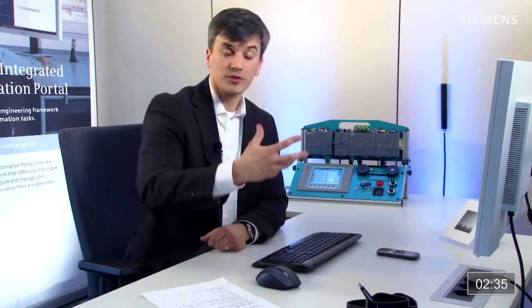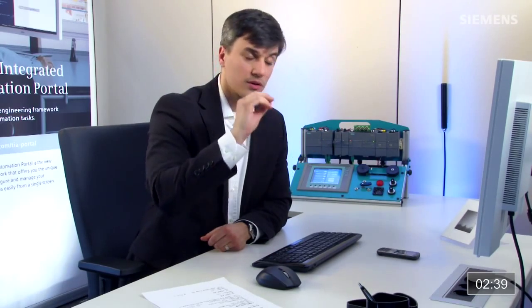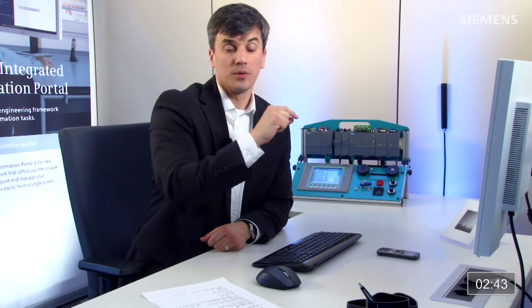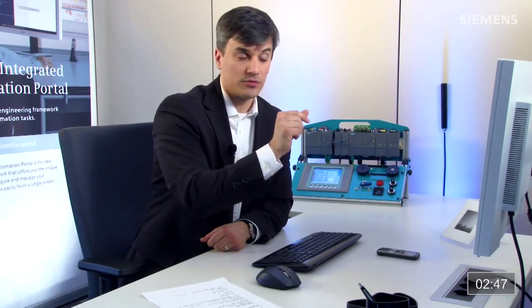So the next step is we want to give focus to the PLC and click the download button. Ultimately, if you think about what we've been able to do, we were able to scan the Profinet network, find this physical hardware, including this new GPRS module with all the other signal modules, and all we had to do was change the attributes and click download, and we have a fully functional system on the cellular network at the same time.